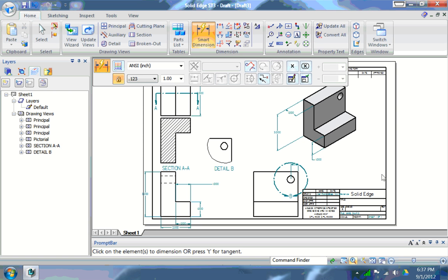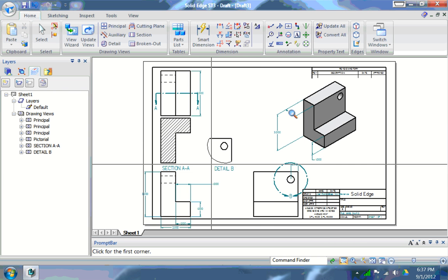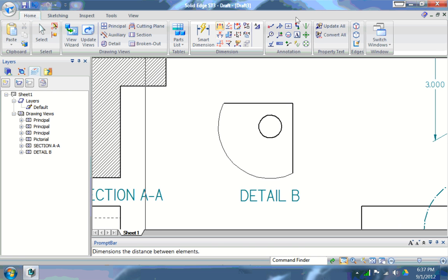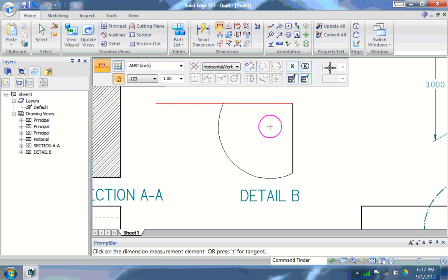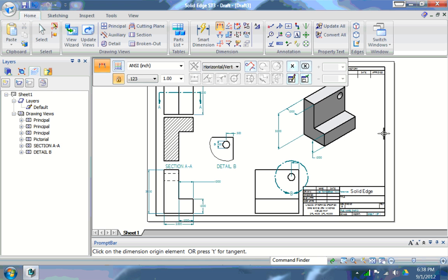If you want to make changes to this one, because we've made a detailed drawing of it over here, you can zoom in on it and start positioning dimensions, just like the diameter of the circle here, and then put some more dimensions on and organize things to make your drawing look really nice. Once you're done, you're going to want to save it again.